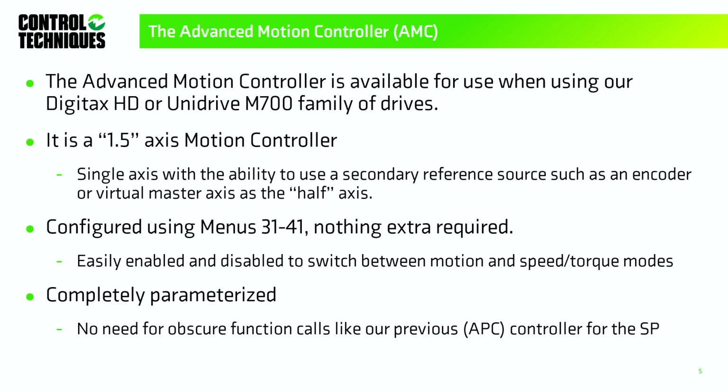The nice part about the AMC, as opposed to our previous version, which was the APC, which was part of our application module, is that every part of the motion controller is parameterized. I don't know if anybody's used the APC before with our SYPT software, but the APC required some sort of obscure function calls in order to use it. So the beauty of the AMC is that it's completely parameterized.